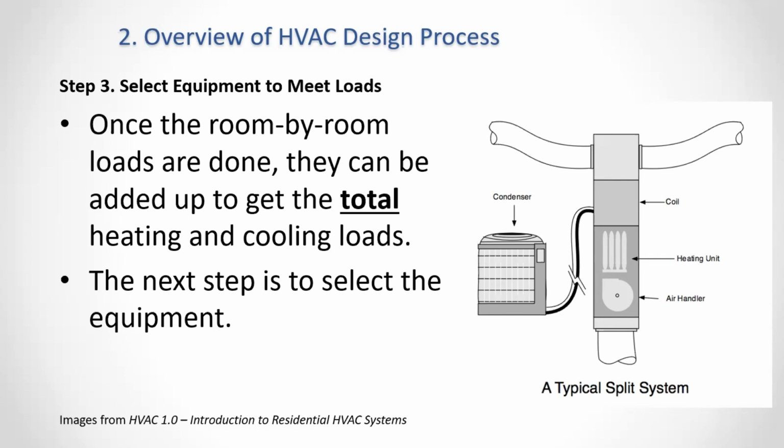Don't oversize the equipment. Oversized equipment will not maintain comfort, it will cost more to install, it'll cost more to run, and it'll probably fail sooner. Those are four really bad reasons to oversize equipment. Undersized equipment, even if it's really undersized, is only not going to work on the very hottest days. And it'll still work a little bit. It'll help cool the house. It may not keep it at 75 when it's 105 outside, but for the rest of the time, it's going to work fine. It's going to work great, and you're going to have lower energy bills.